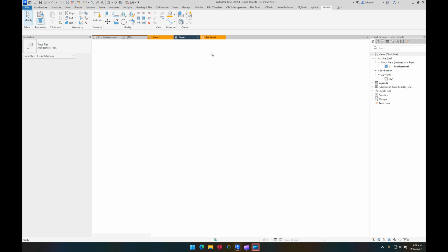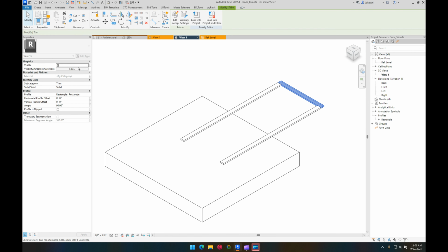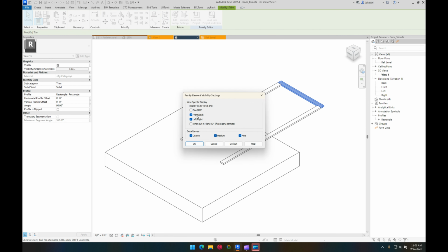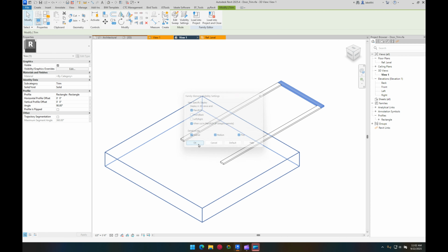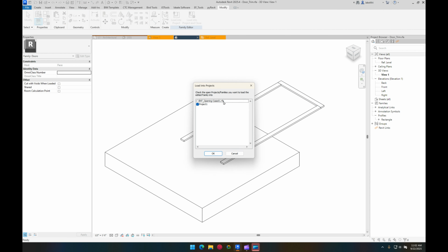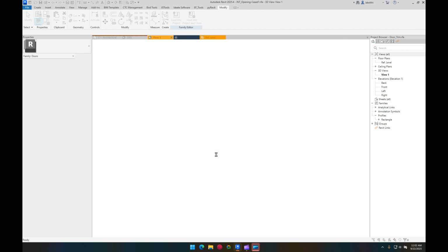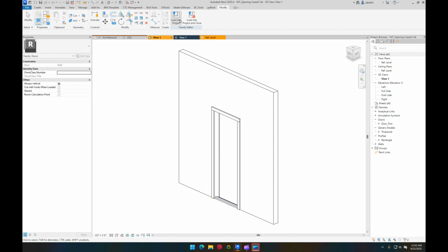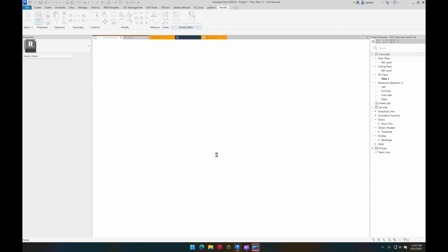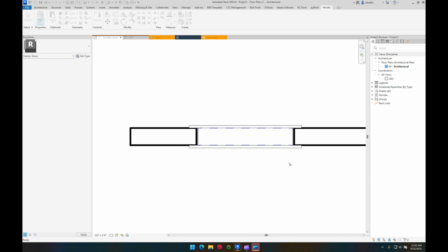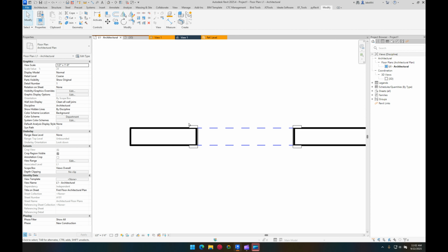And the reason for that is because, again, it's oriented wrong. So what we need to do is change the orientation, because it's going to be flipped. Instead of what's going to be in the plan, it's going to be reoriented. So we would be seeing the right, the front, and left. You'd still want to be able to have it seen in plan and cut plane. But now if we load that back in to the host family, and then we reload that back into the project, and where we're existing, you see, look, everything is working properly. So we don't have that object showing. We don't have basically the top of the casing showing up.